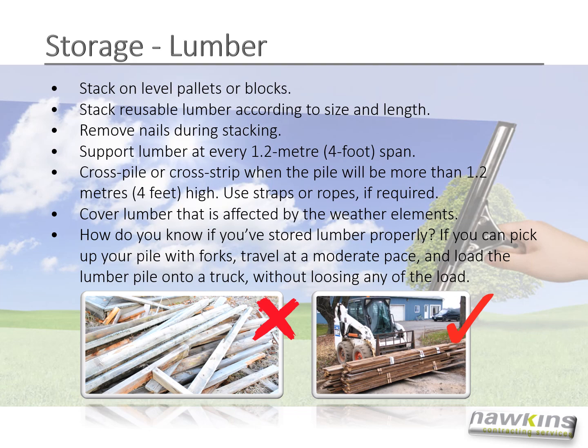When storing lumber, stack on level pallets or blocks. Stack reusable lumber according to size and length. Remove nails during stacking. Support lumber at every 1.2 meter span. Cross pile or cross strip when the pile will be more than 1.2 meters high, and use straps or ropes if required. And cover lumber that is affected by the weather elements.